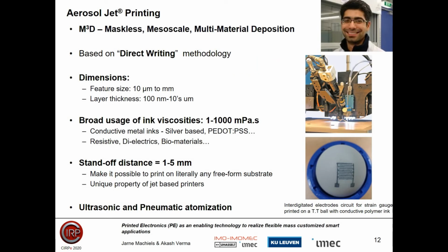Aerosol jet printing is a mass-class mesoscale multi-material deposition technique. It's based on a direct writing, non-contact methodology. The feature size of the printed pattern ranges from 10 microns to millimeters, whereas the layer thickness ranges from hundreds of nanometers to tens of microns.